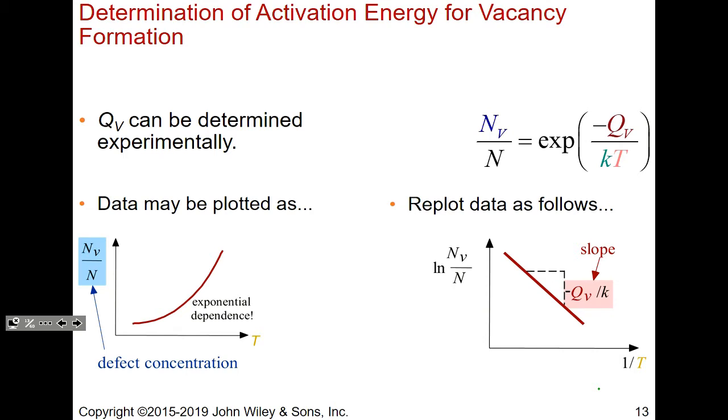And so we talked about how there could be 10 to the 17, let's say the concentration, some ridiculously high concentration of vacancies because it's thermally activated. So at higher temperatures, you're going to have immensely more vacancies than if you were at room temperature, right? It's thermally activated. So the more energy you put into the system, you're going to induce atom hopping.